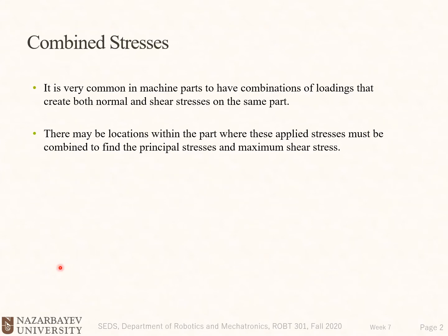Combined stresses. It's very common in machine parts to have combinations of loading that create both normal and shear stresses on the same part. There may be locations within the part where these applied stresses must be combined to find the principal stresses and maximum shear stresses.